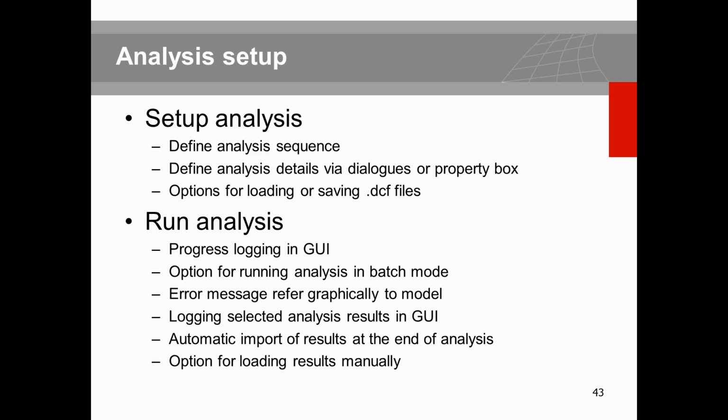Moreover, you can save the whole model as a DIANA project file, DPF, and when you load it in DIANA, you can directly see all the settings associated with the post-processing and the settings of your property windows. Everything automatically gets updated on the screen.